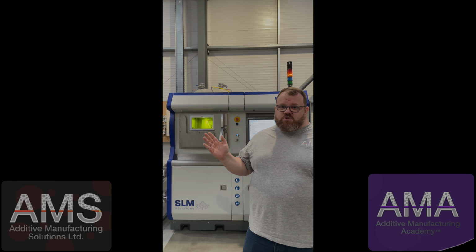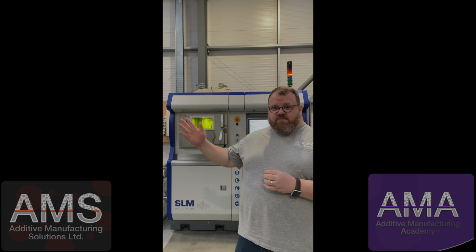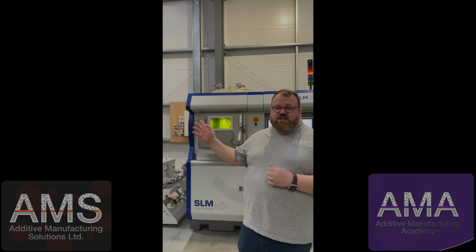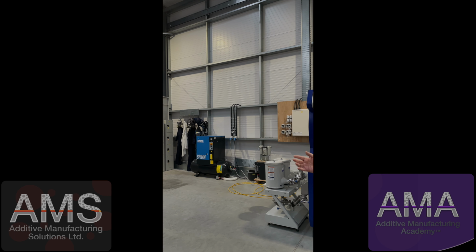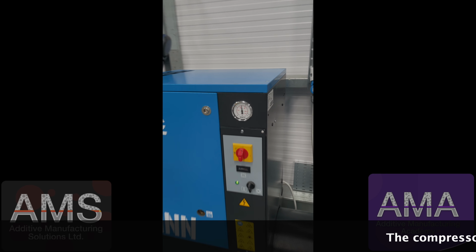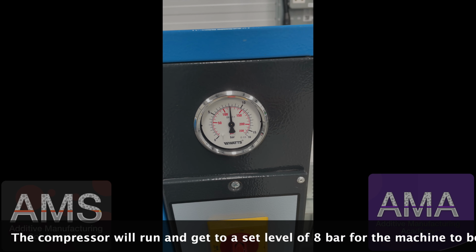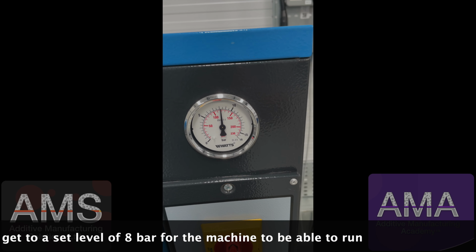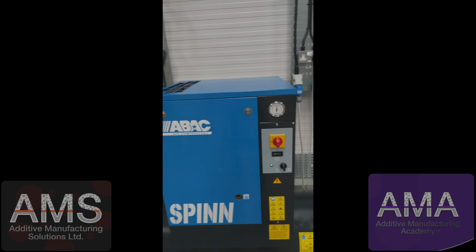This is our SLM Solutions SLM 280. So let's first have a look at the architecture and the infrastructure that's needed before we even think about how the additive manufacturing process of powder bed fusion works. Firstly, over to my right, you can see the installation of compressed air. We have to make sure compressed air is fed into the machine for its safe operation. The compressed air is fed through a dryer before it's fed into the machine to keep the laser system cool. There's also a separate water chiller to aid this process.